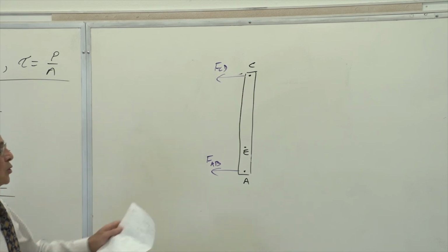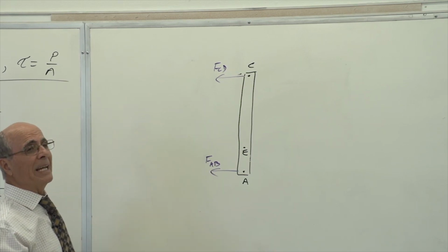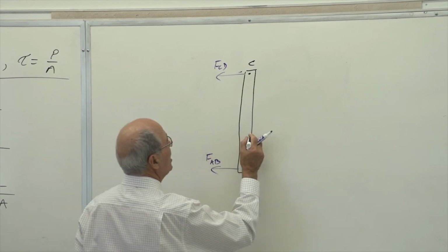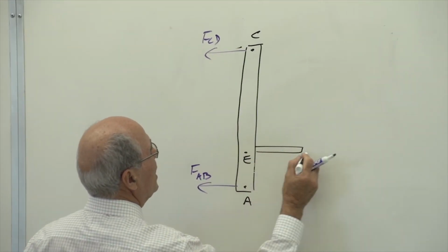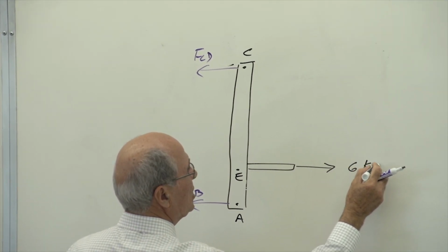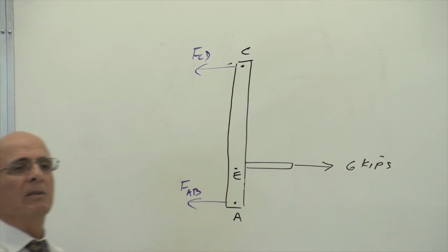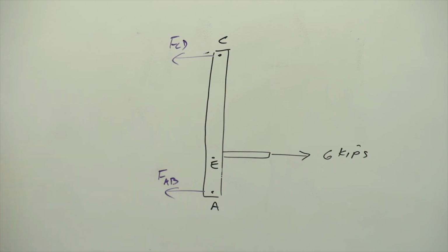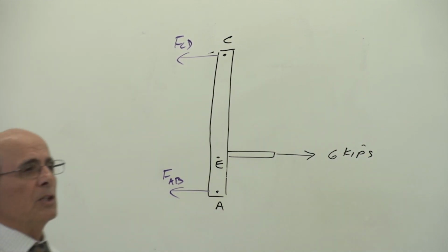Yes? So I have put these two under tension mode, and it is tension mode. Why? Because there is a rod here, and you are pulling that rod with 6 kips, or 6,000 pounds, here. Yes or no? Can you find these two forces? This is the static part of it. So the free body diagram of that object there, that vertical rod, is your static part. Correct? Can you solve it? Of course, it cannot be any simpler than that.